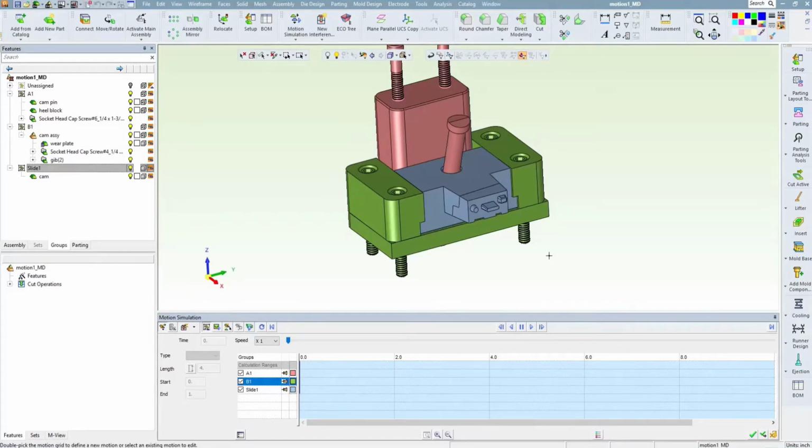Rule 3 states that one of the groups must be locked in place. Without a motionless group to push off from, the reactions of the other forces cannot really be determined. The push pin in the motion window is how to set this. It's a simple but important step that must not be overlooked.